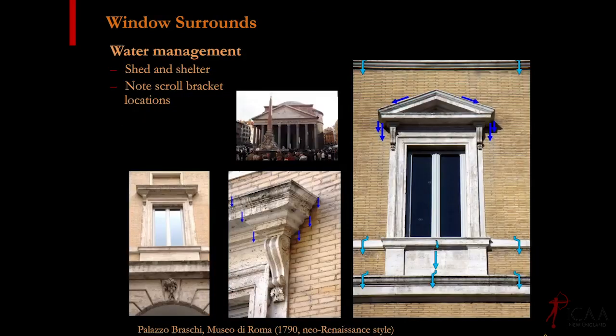So if you think about water that's hitting this facade, what's hitting here is in part absorbed by the brick and is in part cascading down over the surface. The glass is totally impervious and non-absorptive, so everything that hits this window is being funneled to this point right here. And that's where you have a very, very thin wall underneath. So what sort of magic happens to make this work and not just have a massive amount of leakage and damage under this? You need a really good sill detail. So they really needed to think about this.